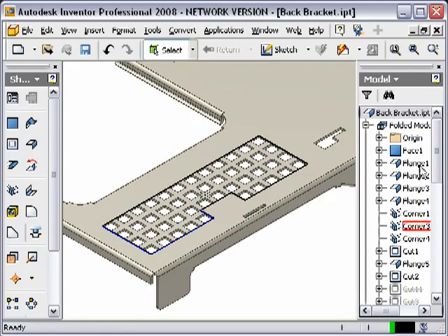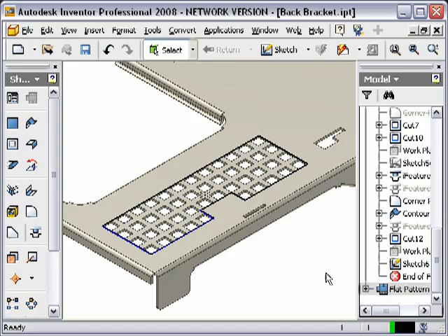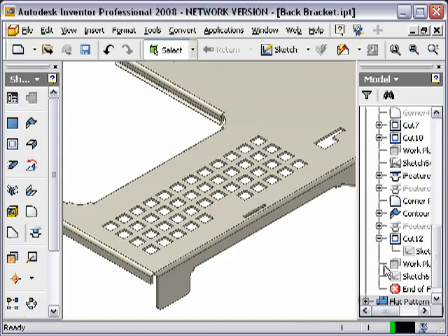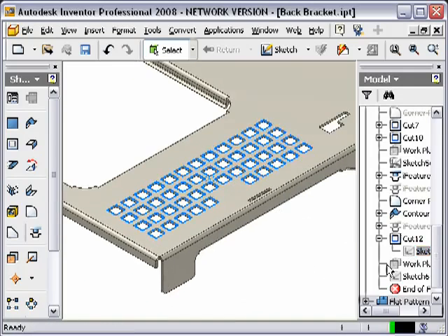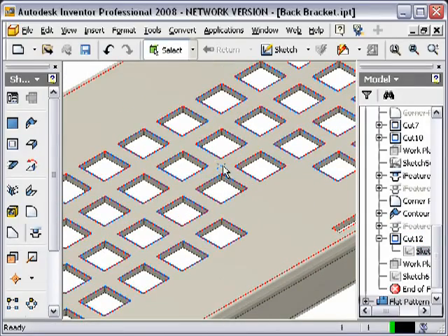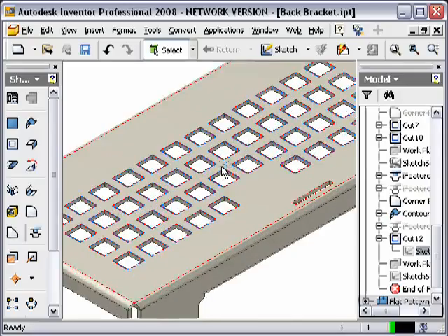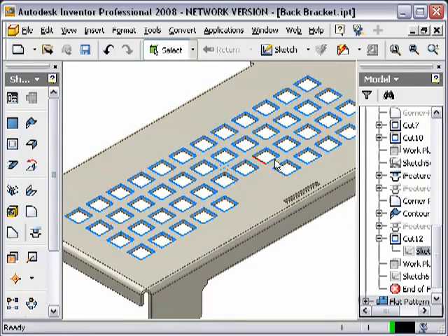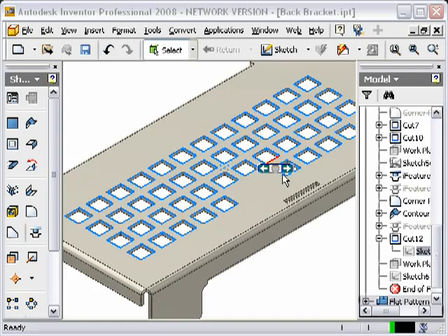Before I jump into the actual punch, let's take a look at the setup that I've set up here. You'll notice that I have a sketch, which we'll talk about a little later, that's overlaying the feature that I want to create as a punch. I'm going to turn the visibility off for right now. You'll notice that underneath the actual cut, I also have a sketch with a hole center, or a center point. So in my initial sketch, I need to have a center point and then create the feature that I want to eventually roll into a punch.